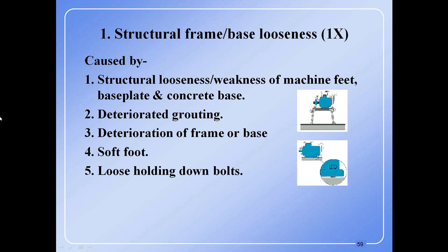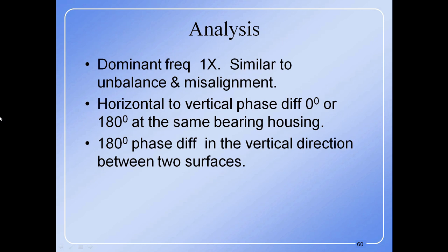Analysis. Dominant frequency 1x, similar to unbalance and misalignment. Horizontal to vertical phase difference of 0 to 180 degrees at the same bearing housing. Third point, 180-degree phase difference in the vertical direction between two surfaces.